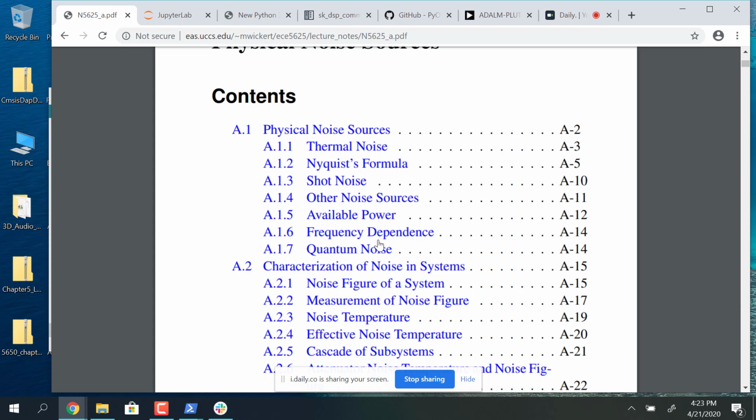Physical noise sources. So we'll be looking at modeling thermal noise primarily in receiver front ends, and we'll tour all the way through this and end up with link budgets for radio links. We'll have an application example with antennas in it and effective noise temperatures, noise figures, and things of that sort. It's pretty high level, and it fits well with communications theory, but Professor Song talks about it in her EMAG classes some too. There's an overlap between the different domains.